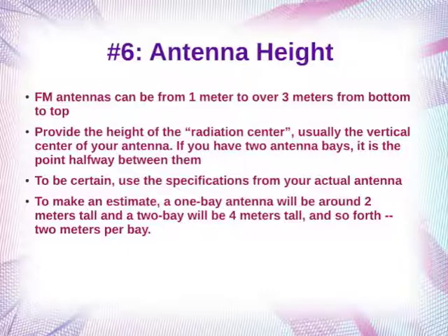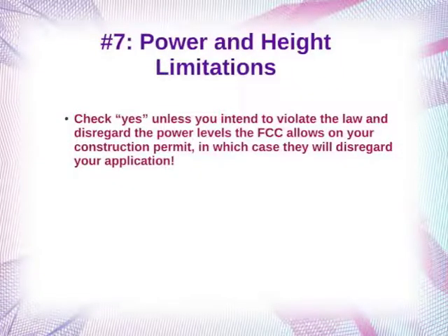You can stack them on top of each other and get some good properties from that at a somewhat greater expense, and desirable transmission properties, which I'm not going to go into here. Practically speaking, a lot of people will be using 2-bay antennas. Some people will go up probably to 4, but I don't expect to see anything bigger than that. If you look at commercial transmission sites, you will often see that they will stack them sometimes as many as 13 high for a UHF TV station.